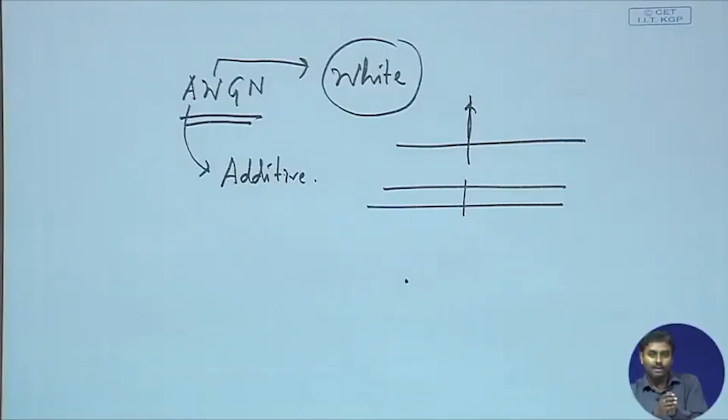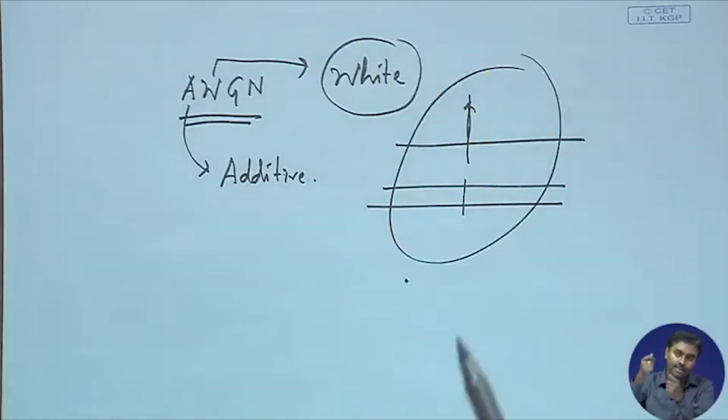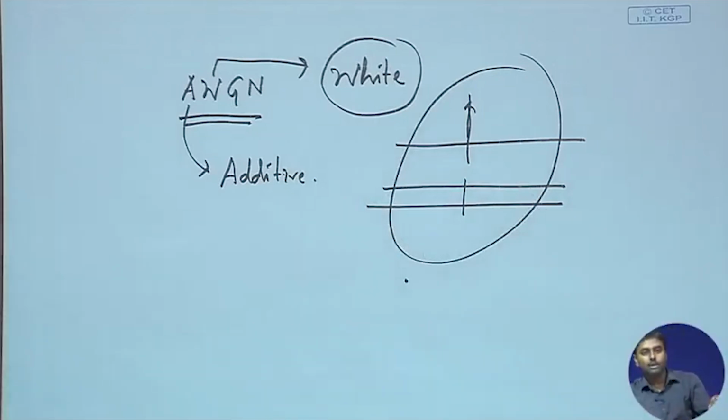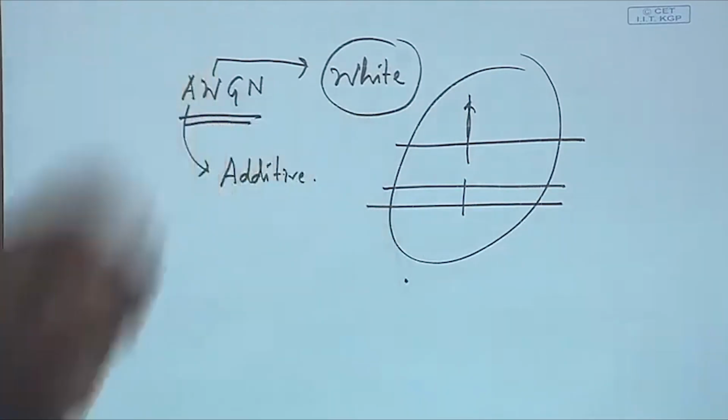Okay. So, same thing, white noise is created by an equivalent noise component at every frequency, as many frequency components as you can think of up to infinity. So, all those frequency components are equivalently present in this particular noise. And because the noise is like this, it just comes from the autocorrelation function of our understanding. Because every frequency component is equivalently present, we call this white noise. So, most of the time we will be considering white noise.